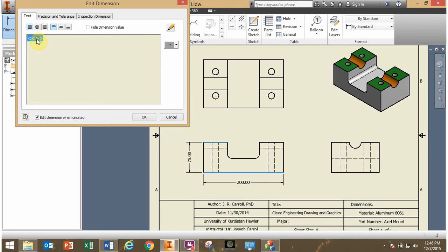So these little greater than, less than symbols here say grab the dimension that you already defined when you made the part. Alright, so you never want to change this because you want this to be linked to your part. But I could add other text here. I could say this is like a height or something.